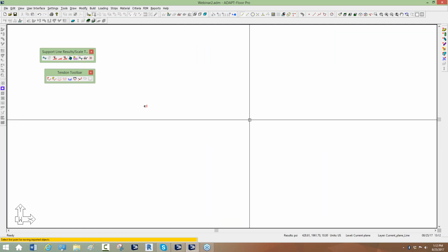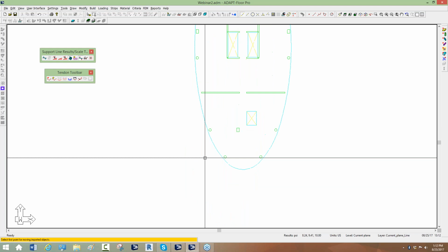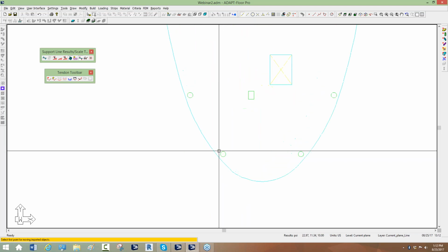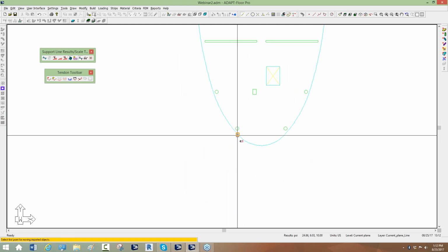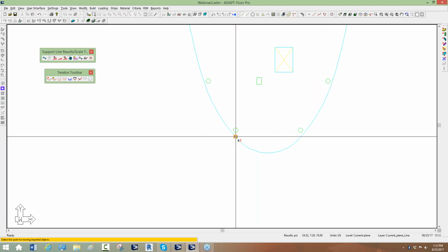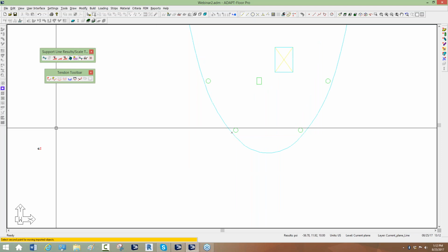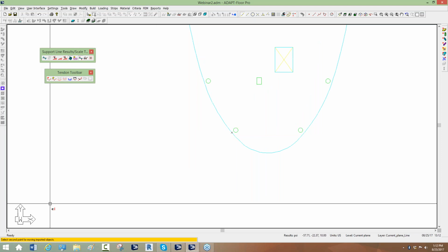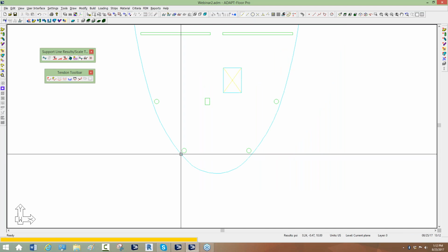So to get the drawing file back, I'll first zoom extents, and I'm going to insert this column here. This will be my reference point, my first point. Well, I can't select the center of that, so let me just select an edge here that's snappable. So I'll select this point, and I'm going to move that. I can either enter the next point graphically, or I can enter 0, 0, and then the Z dimension is 10. We're on the current plane, which by default is 10 feet above the base level. So we'll say 10, enter, and that moves that point to 0, 0, 10.